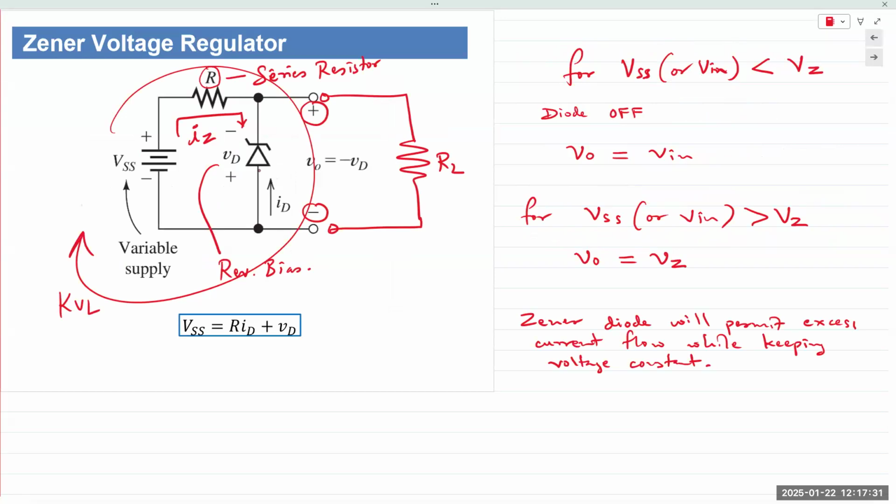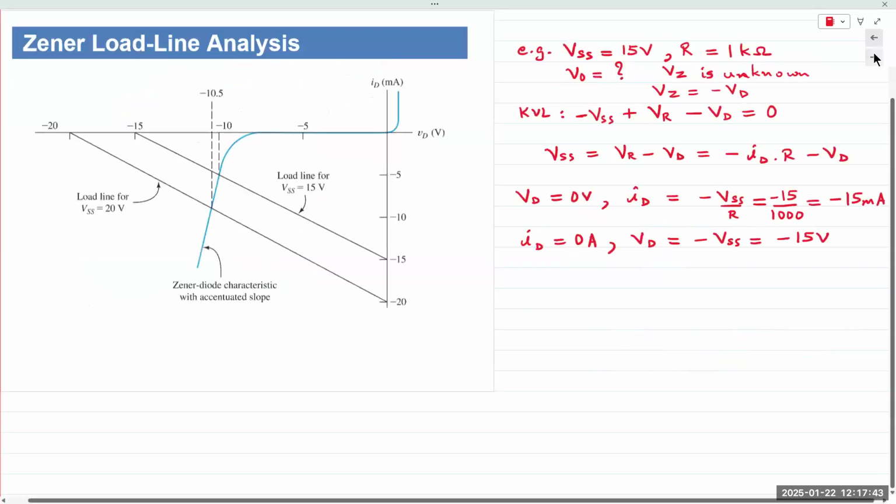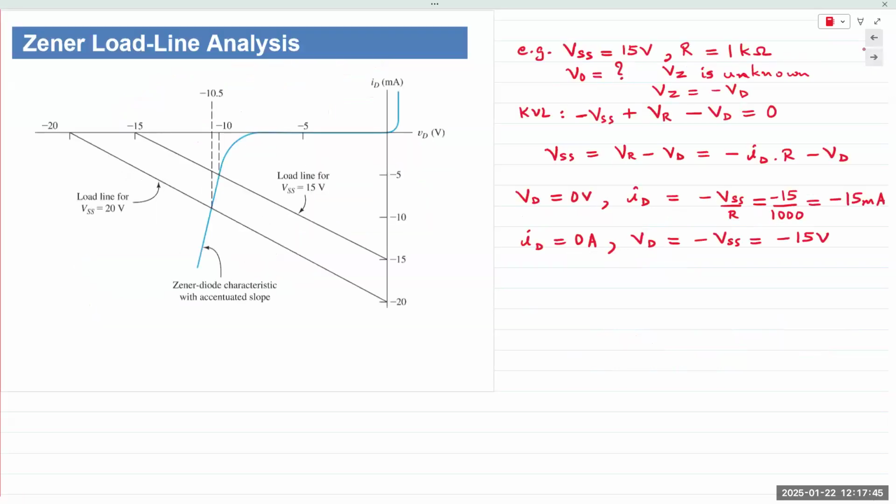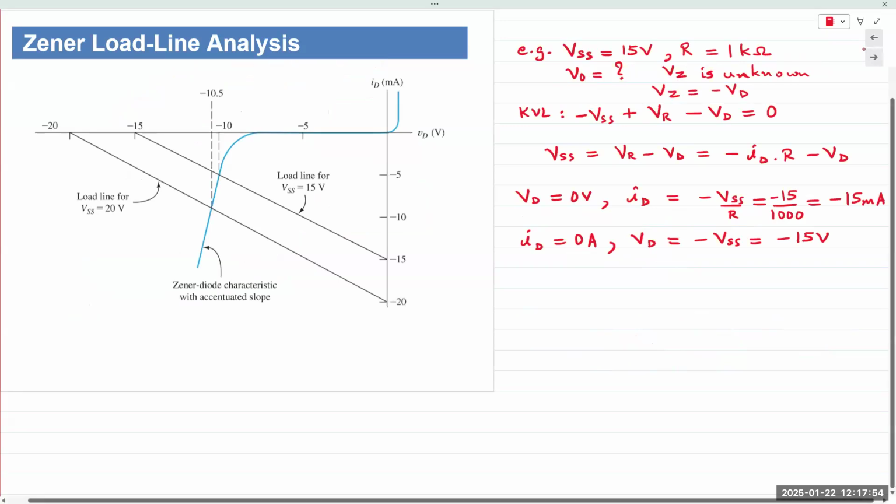So we say diode voltage and diode current for a Zener diode is negative, but we refer to Zener voltage and Zener current simply as positive. And that sometimes gets confusing. Okay, and again, just for this example, particularly, I will stick with a negative. But when we do the regulator, the next example, we'll just stick with a positive convention.